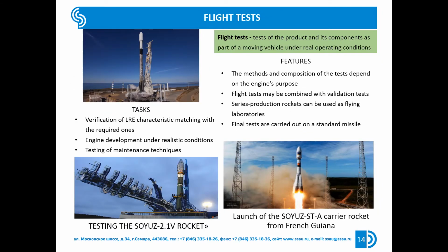Flight testing is the testing of a product and its components as part of a moving vehicle under realistic operating conditions. Although flight tests are less informative than ground tests, due to the limited number of measuring instruments and telemetry channels, as well as their high cost, verification of joint operation of all elements and systems of a liquid propellant rocket engine and flying vehicle under operation conditions is obligatory.